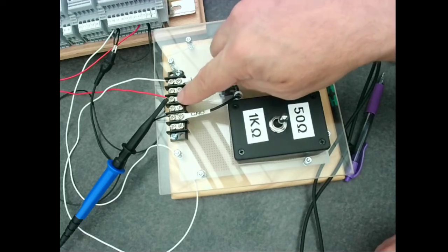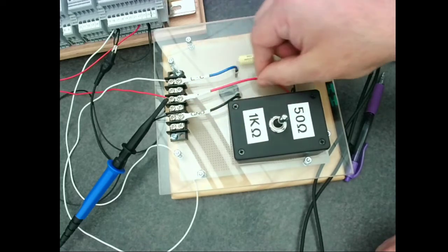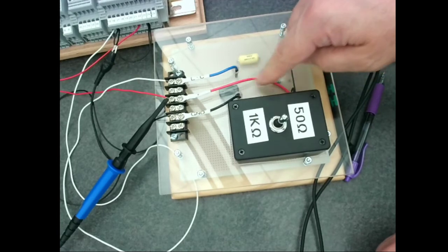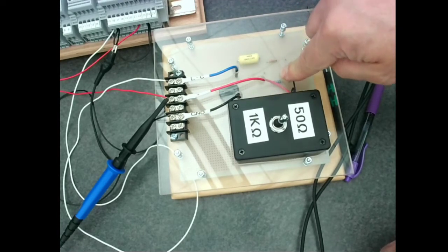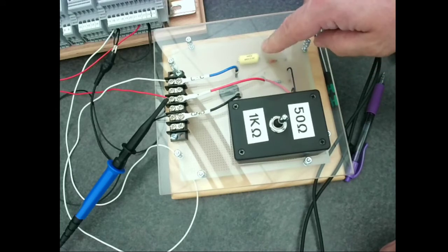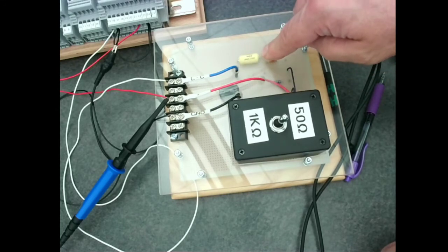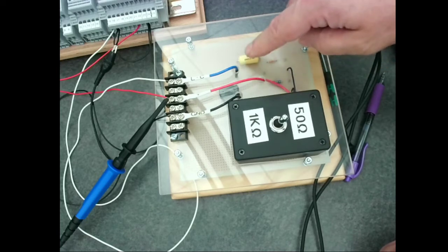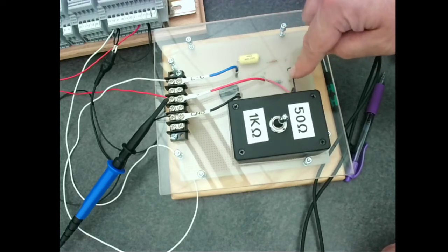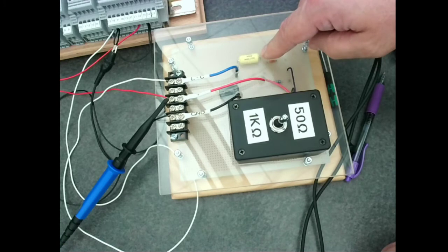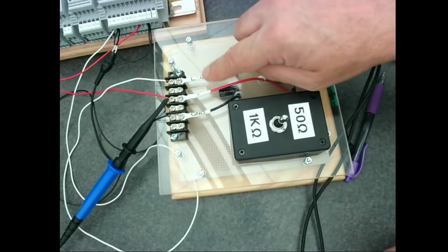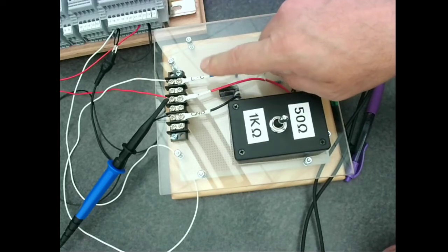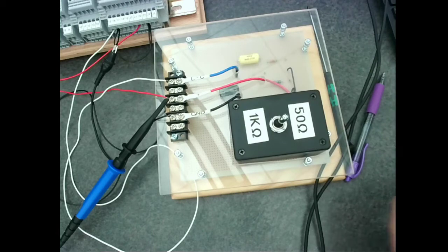And so the input is going to come in here through this red line, which goes into one of the 2 resistors, depending on the setting of the switch. And then the other side of those resistors are attached to the coil. So again, it's a series connection, so it's going to go through the resistance, then through the coil or the inductor, and then to the capacitor. And then what we're going to do is measure the voltage across the capacitor. So that's going to be our output voltage.